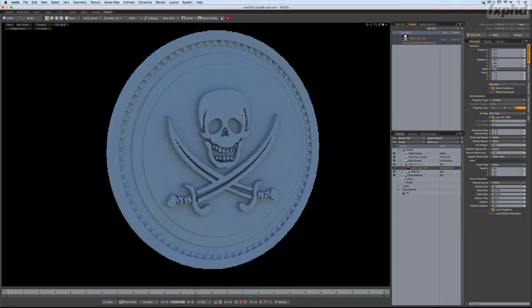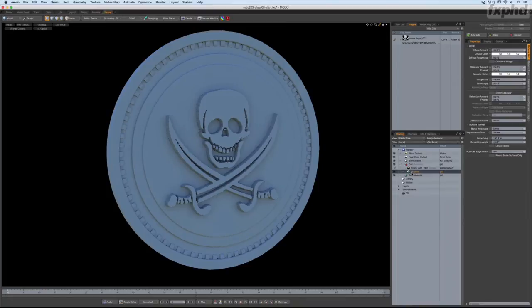Now, it's really super extreme, so this is where you're going to have to kind of dial it in a little bit. As a reminder, you can find all of the displacement distance inside the material that's responsible for shading all these pixels. And right now, my displacement distance is set to 20 millimeters, which is, in my opinion, maybe a little too high. So let's half it down to 10 millimeters. Force preview to update here in a second. There we go. Yeah, and now we're marching something that's closer and closer and closer to what my imagination has come up with.